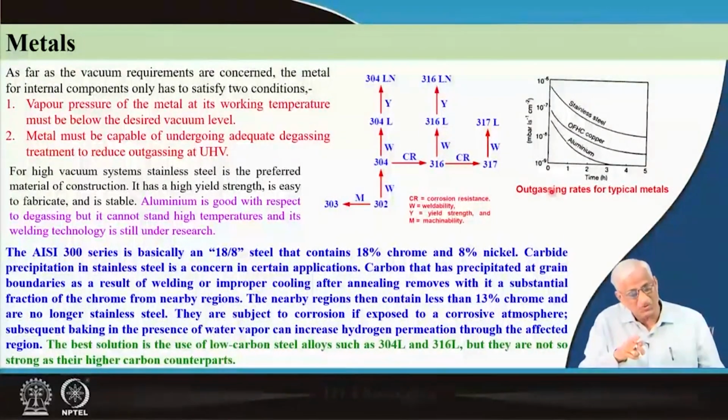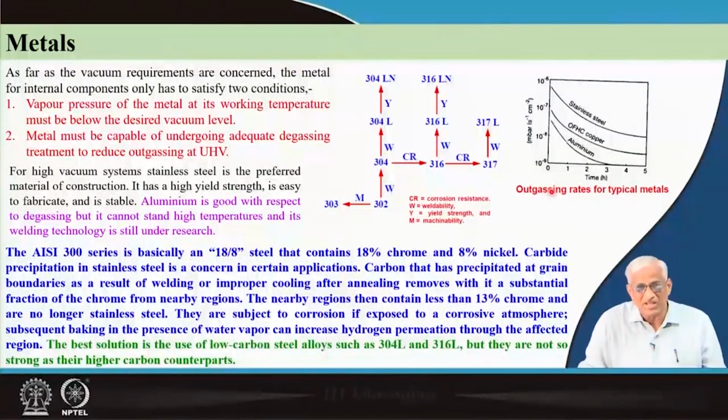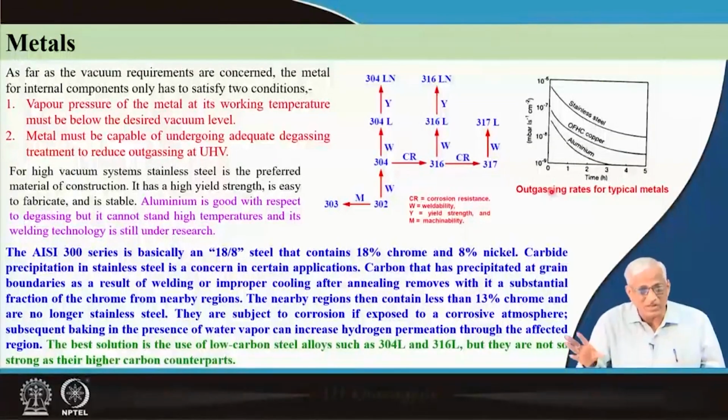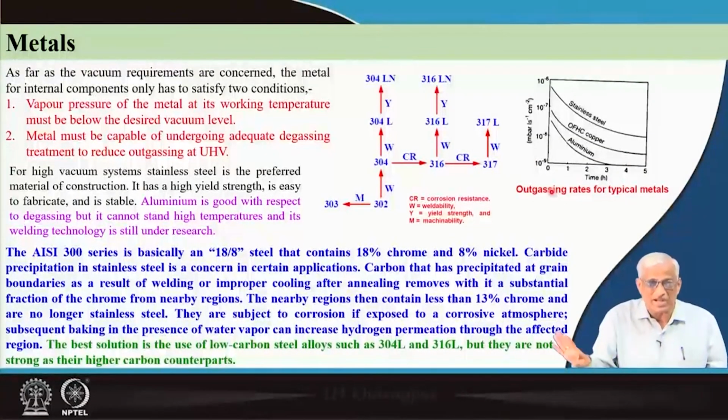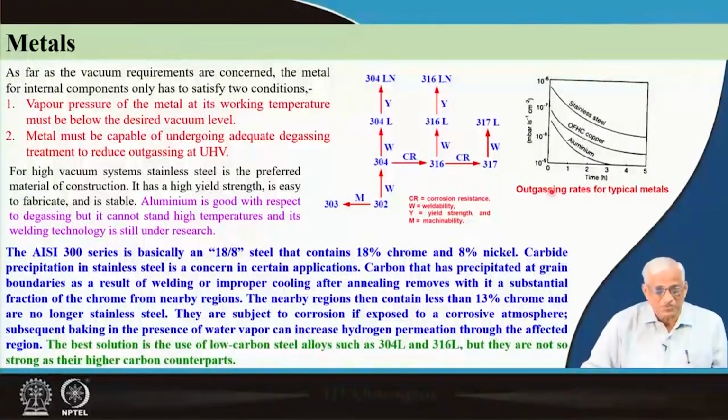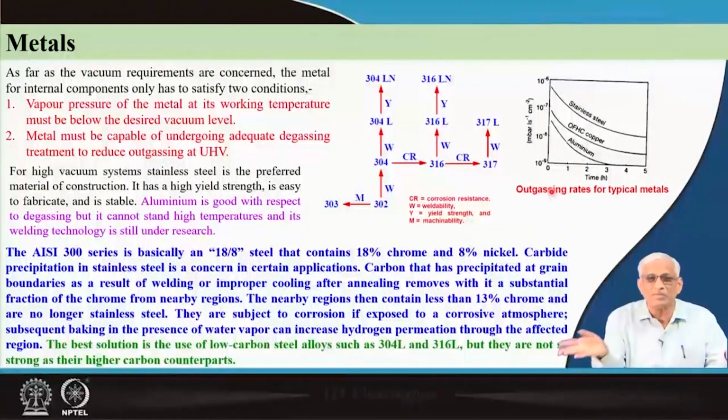But if you are able to degas it fast using some forcing, like ion beam etching, infrared light, or baking, or purge it with a gas, clean it, then start your application. So, it should be possible to degas it easily also. First is, it should not degas or have too much gas content. Even if it is there, we should be able to remove it. Under vacuum, if you remove it, there will not be gas there again.